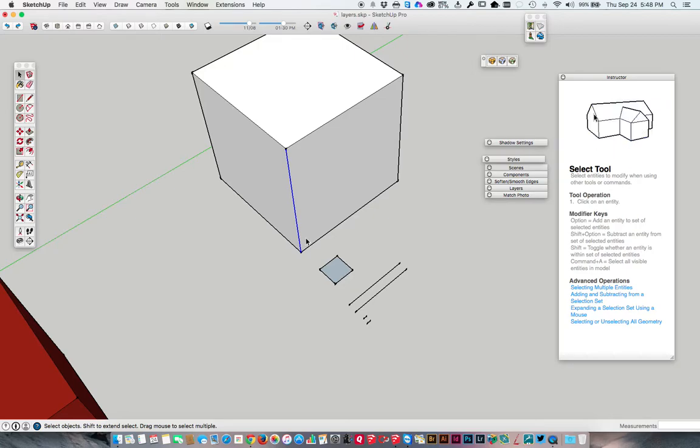And that one thing was the only thing that was entirely contained in this window. You can see that the little window is touching the other lines of the geometry, but they're not fully contained inside my window. And so only this line was fully contained inside my selection window. I'll just click somewhere outside of the geometry to deselect.